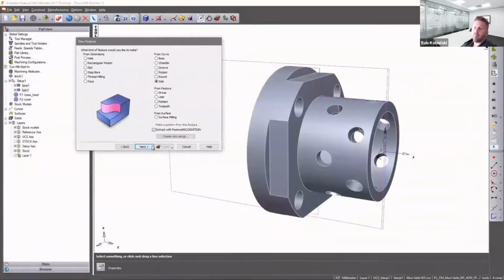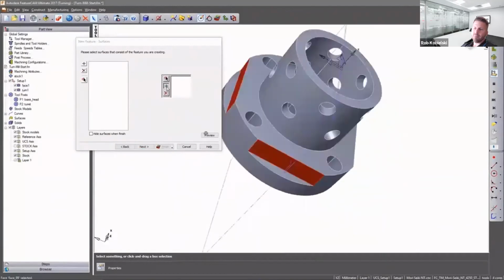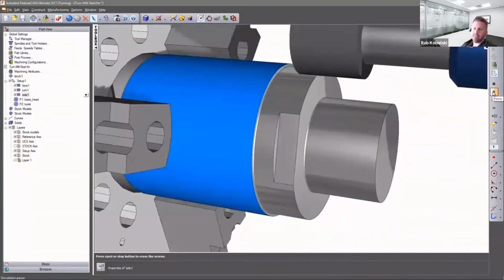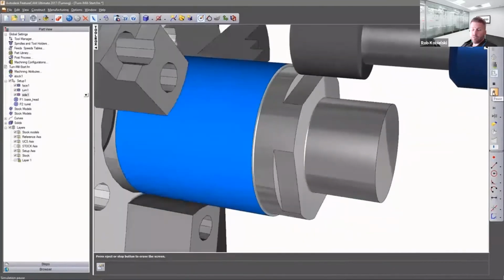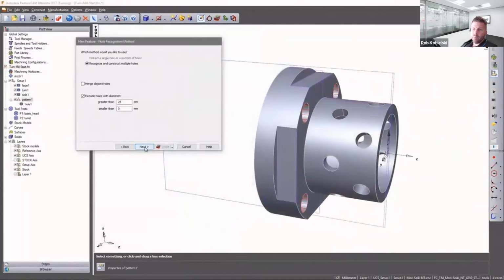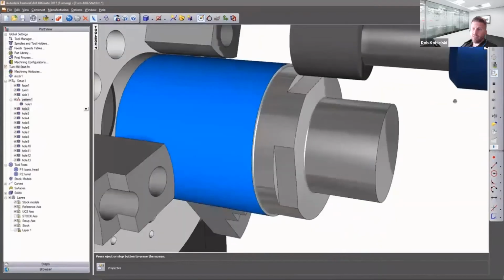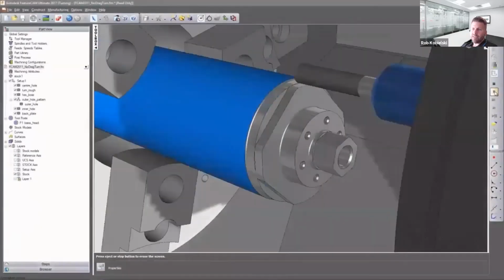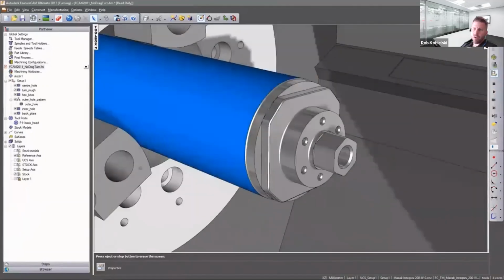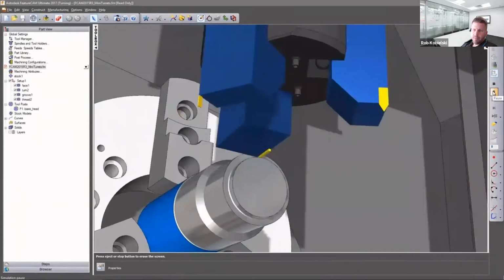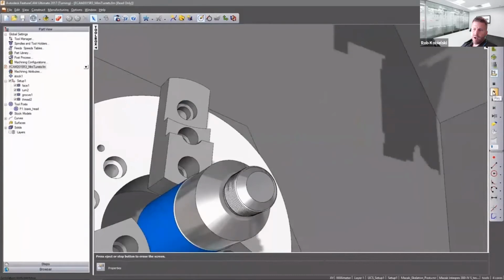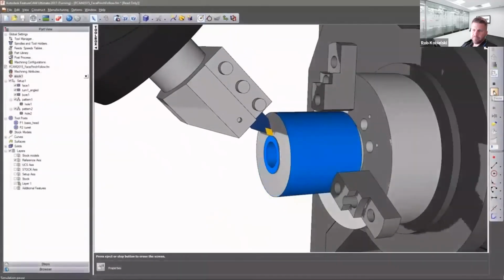Fusion 360 with FeatureCAM also supports turn mill centers by enabling both milling and turning features to be created in the same document and machined in a single setup. Choose whether you want to create turning or milling features using either dimensions from a blueprint, imported 2D curves, or 3D solid model faces. Recognition can be used to automatically detect features on the axial face or diameter, thereby reducing programming times. Milling operations can be quickly switched to using either the C-axis or Y-axis for improved surface finish.